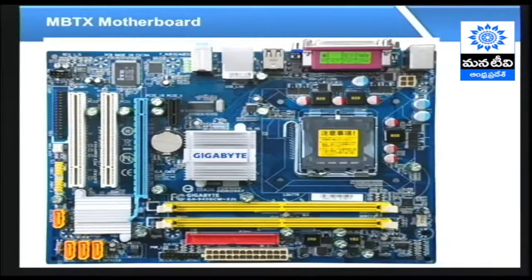Okay. One more chipset on motherboard is south bridge. Look at screen everybody. This is south bridge. The chip which is located near to the RAM slots or expansion slots is called as a south bridge. The south bridge is generally used to manage and control input output devices. If I would like to connect keyboard and mouse or printer or scanner with the help of input output ports, those devices will be managed and controlled by south bridge. Moreover, south bridge is responsible to manage and control expansion or reserve slots.